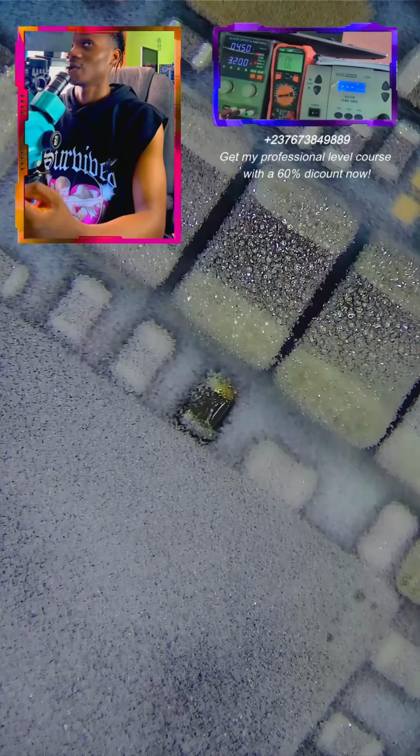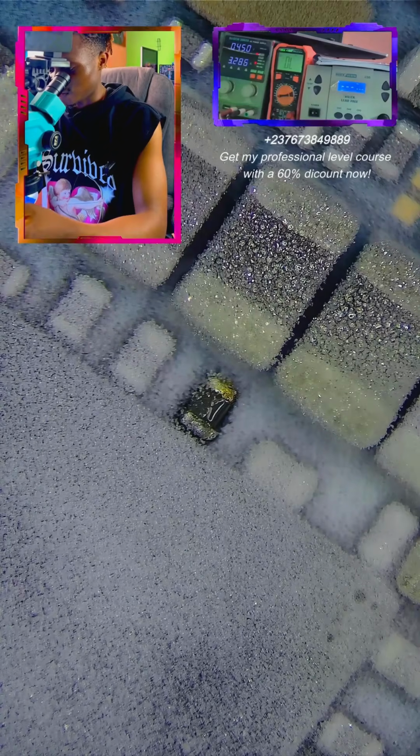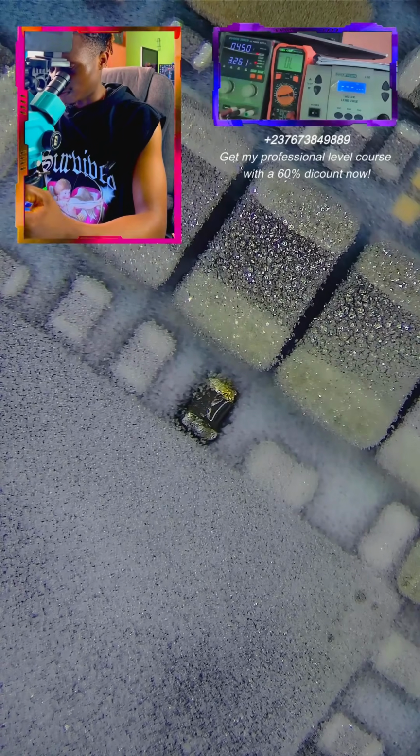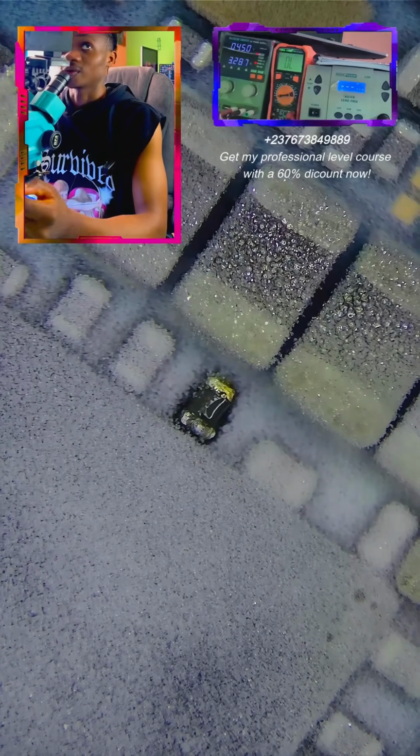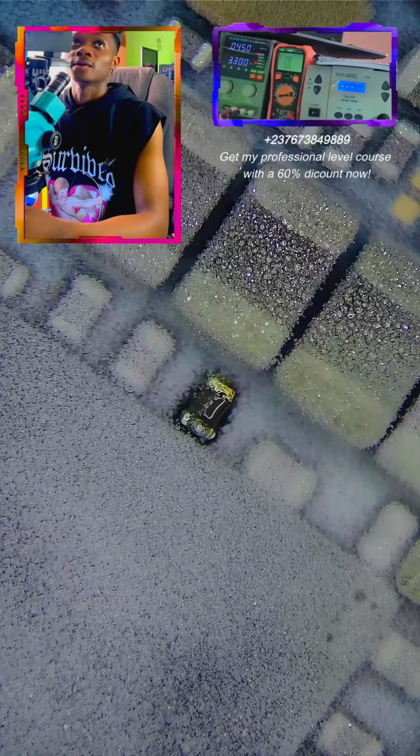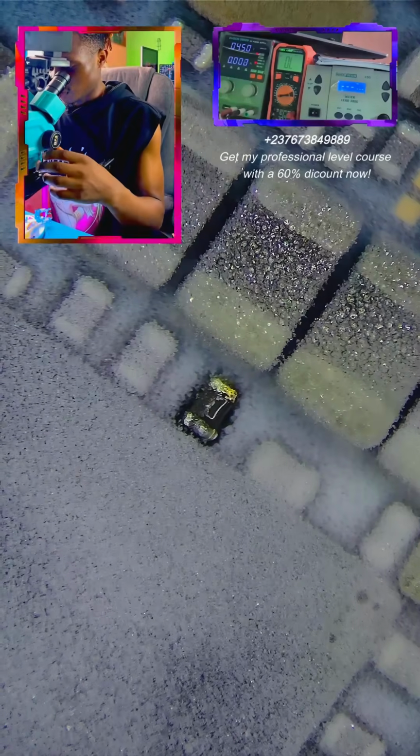Capacitors around the power manager section, in most cases they will heat up just a little bit. At times I increase the voltage to 5 volt to be able to see any capacitor heating up around these sections. I noticed this type of problem in most Pixel phones. So that capacitor is shorting, so let's remove this capacitor, hoping that this is the only capacitor causing the short.